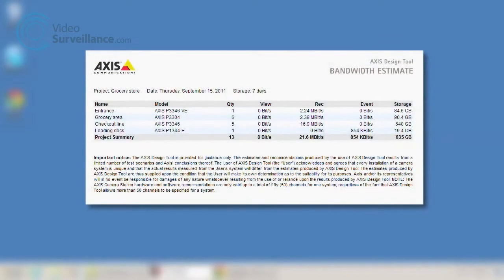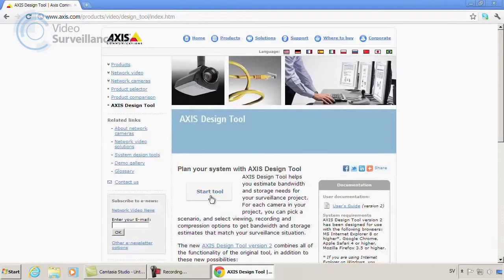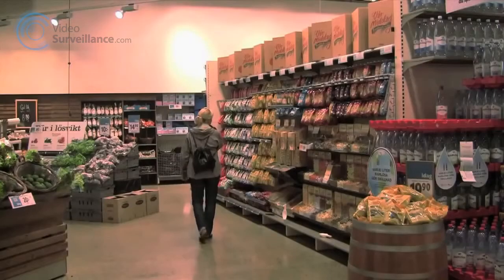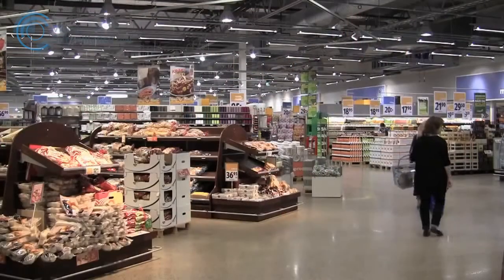Welcome! In this Axis Design Tool video tutorial, we will provide a practical example for estimating bandwidth and storage needs for your installation. The estimates depend on the viewing and recording settings used, but also on the scenario captured. The example we will use is a grocery store.